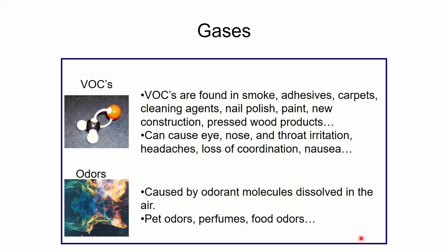There's lots of stuff we can do in terms of odor removal, pressurization control, stuff like that, that we will talk about. There are other gases that are worrisome beyond VOCs and odors. For example, I mentioned earlier carbon monoxide. That's obviously a gas, and obviously I don't want it, but I'm not really putting that into the indoor air quality bucket, generally speaking. That's dangerous, hazardous. VOCs might give you a headache. Odors are objectionable. But if you have a carbon monoxide leak in the heat exchanger of your gas-fired rooftop unit, that's a whole different category of things we've got to deal with.